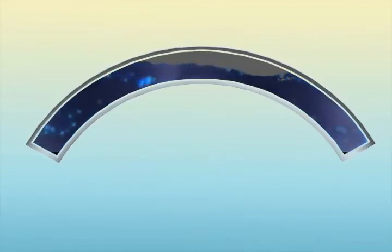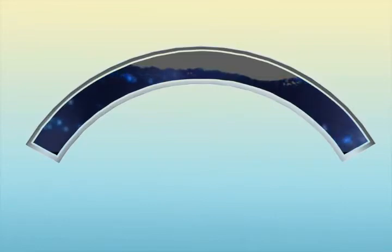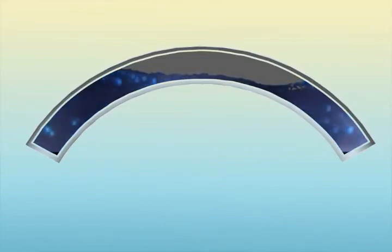The first possibility is a total flow stoppage. If system dynamics are such that the air cannot be continuously removed by the increased fluid velocity and pushed downstream, the system can become airbound, leading to complete flow stoppage. As the pocket continues to accumulate air, a pressure drop higher than pump capacity can develop and stop all flow.